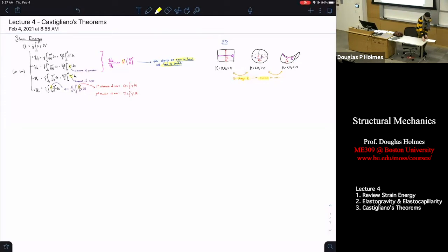So this is a subtle difference in this structure. I just literally tilted the edges by a millimeter, and look at the deformation response. This thing is a huge overhanging cantilever. I let go, and it sags by almost the entire length of the sheet. That's a huge change in structural behavior by changing a very small thing.